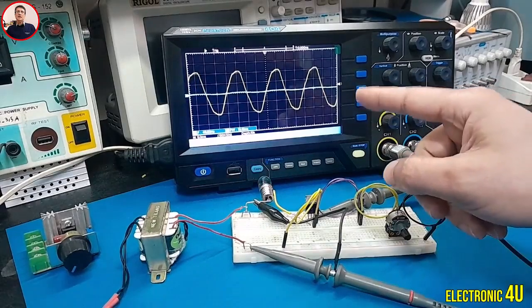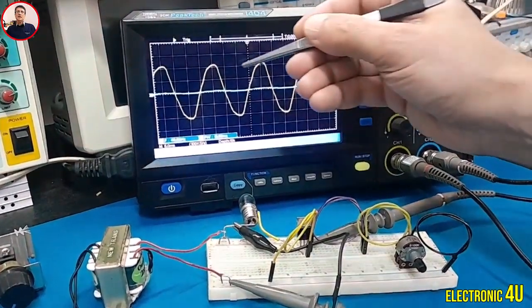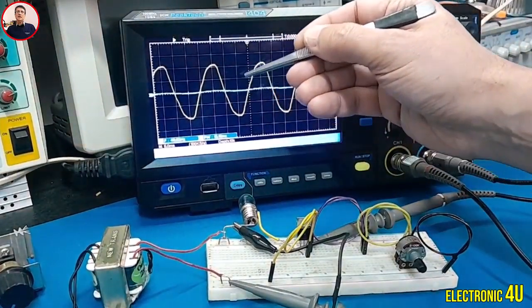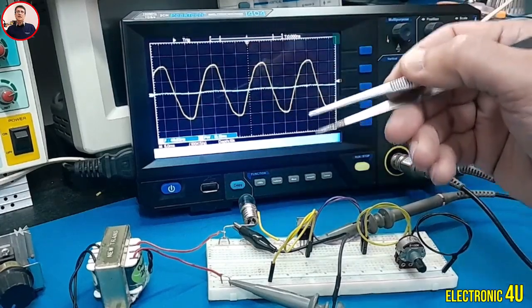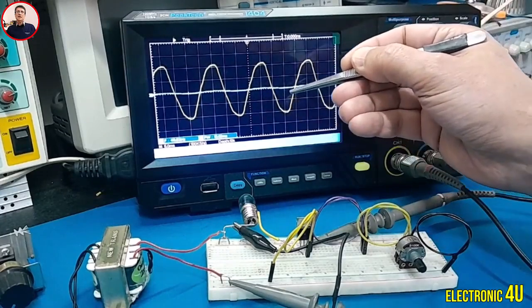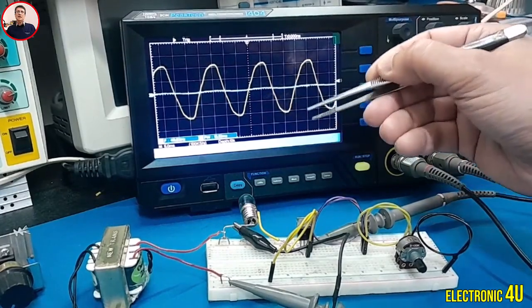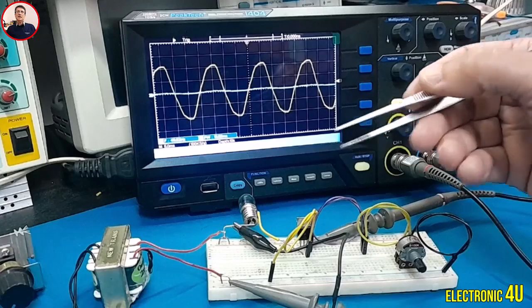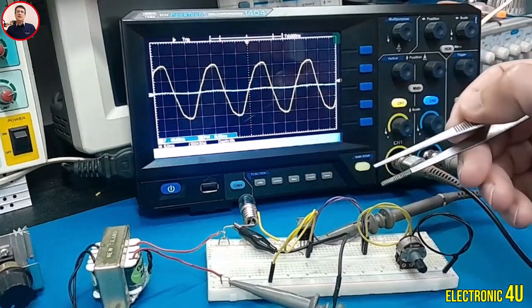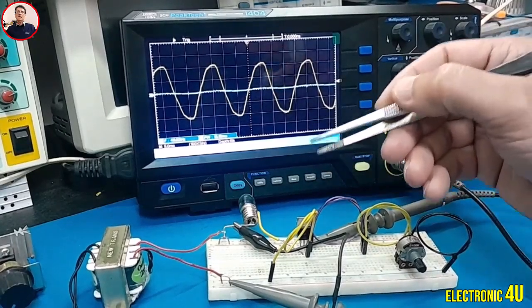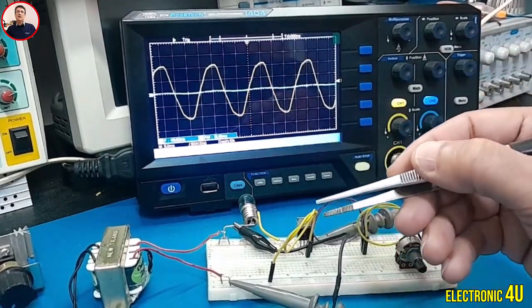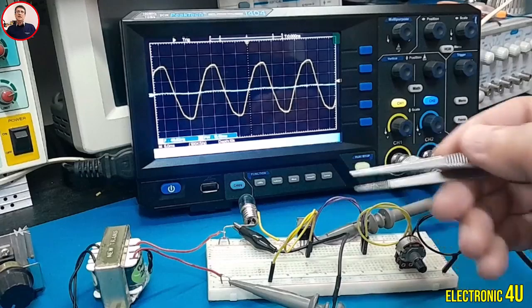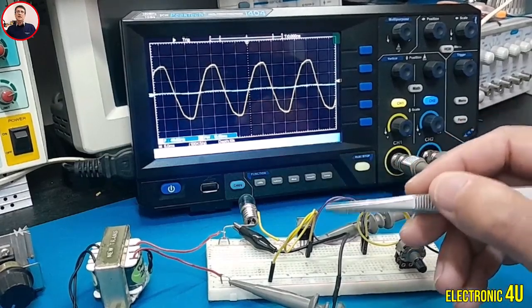Now, pay attention to the oscilloscope. Channel 1 signal is the AC input sine wave, although with a lower amplitude here. Channel 2 signal, depending on where the probe is connected, is either the gate voltage or the voltage across the lamp. The firing angle is usually defined as an angle in the range of 0 to 180 degrees for each half cycle, relative to its starting point.